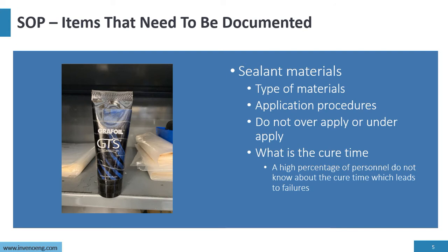Sealant materials: type of materials, application procedures, how to apply it correctly. Do not over-apply or under-apply. And one of the things is, what is the cure time? A high percentage of personnel do not know about the cure time, which leads to premature failures.